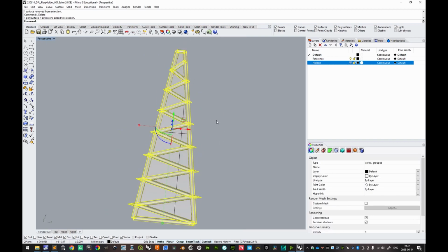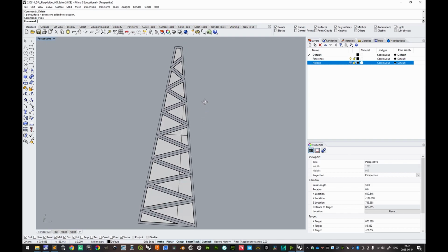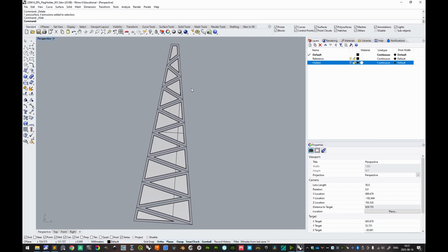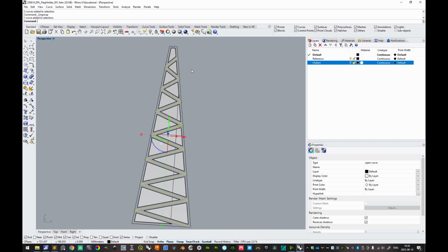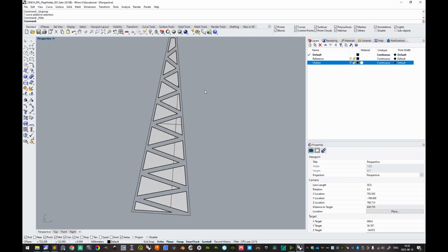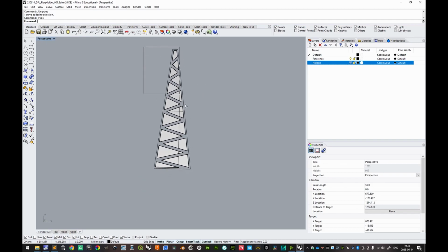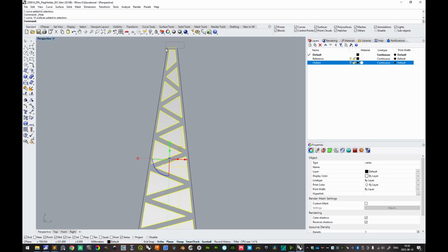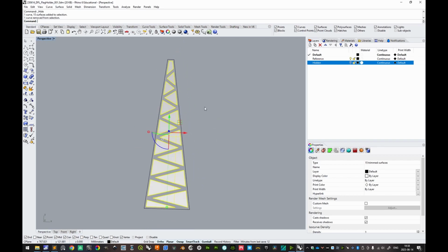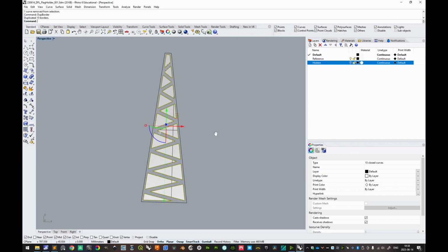And now we can select the pipes and hide the pipes, and now we see here, very good, this is what we want. And then we can select this and do Control Shift G to ungroup. So then we only have that curve there, and that we want to hide. We can Control H, hide that. And then with all of these, here is a nifty thing with the selection from the left to the right, and make sure that you don't select that, but of course you still have it because we exploded. If you hold Control, you can deselect anything that you have already selected. Then you can do duplicate border to duplicate those borders.